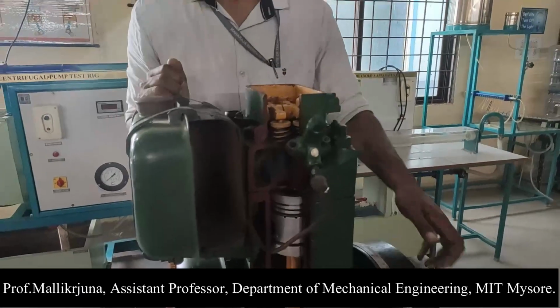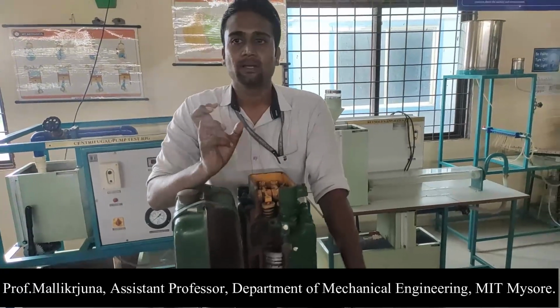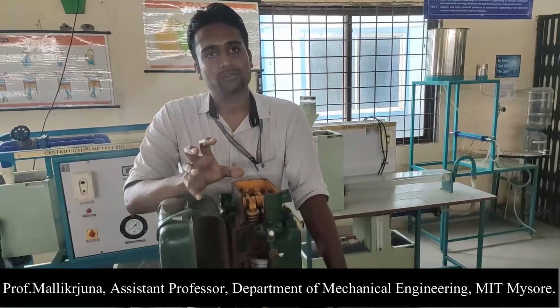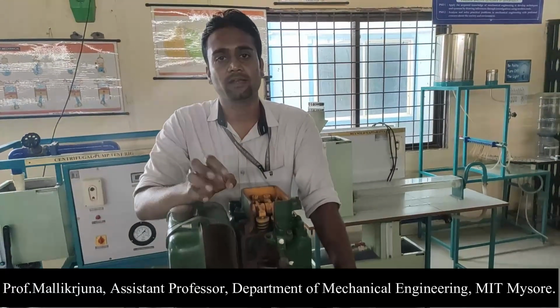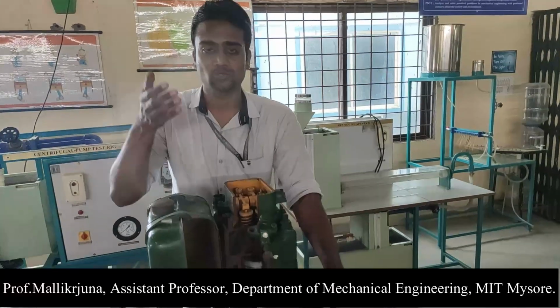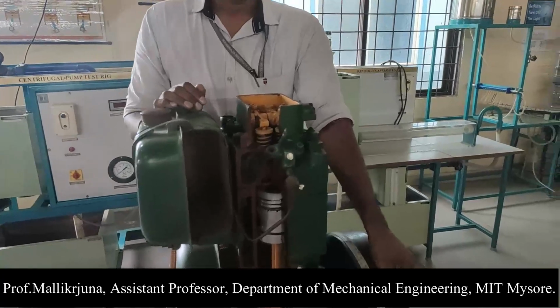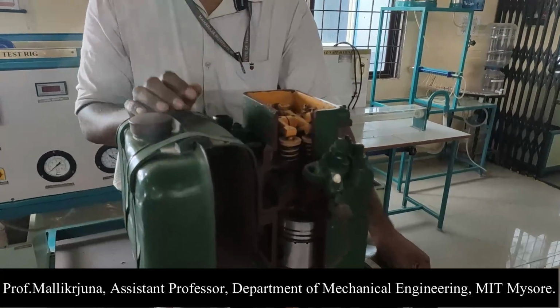Both operations are over. Now, the fuel injector atomizes the fuel and injects it into the engine cylinder. This fuel mixes with the air and starts to burn. Because of that, power starts to generate. The burnt gases apply pressure on the piston. Now the piston again starts to move downwards, in the sense that the power stroke is happening. During that time also, both the valves are closed.